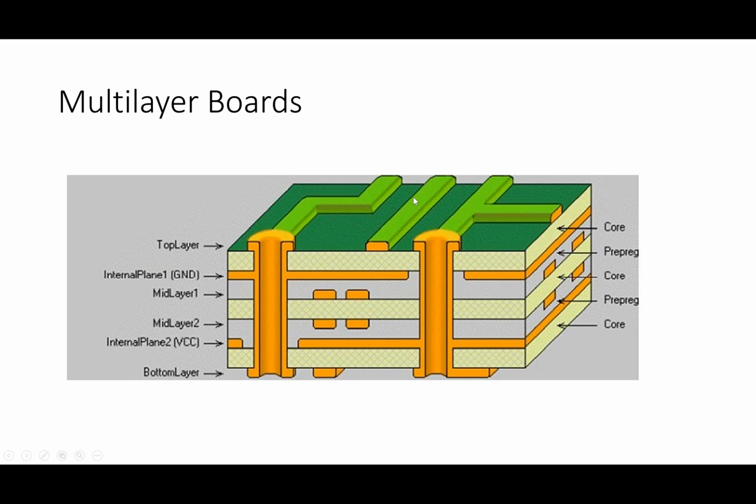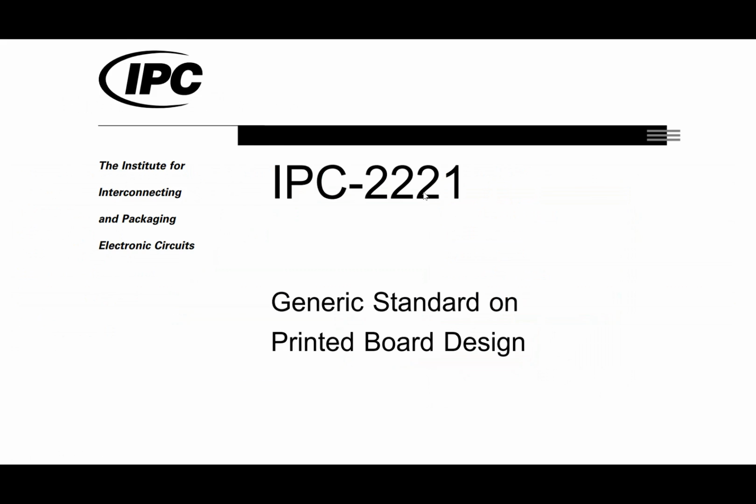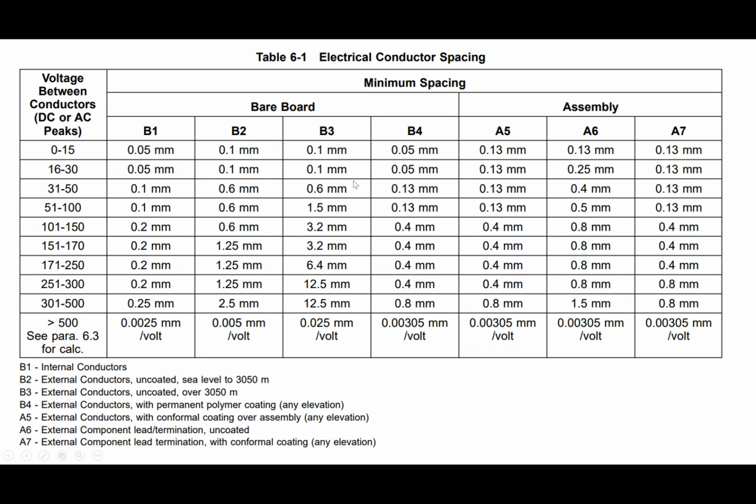There is a possibility when I have an electric field over some distance like this that I can have a phenomenon called dielectric breakdown, where I can actually get some electrons to jump from one side to the other. We want to avoid that. So one of the critical things we have is standards about what the distance between lines should be, and that distance is largely controlled by voltage, because we're trying to prevent that dielectric breakdown that you talked about in fields. So one of the things in that design standard is it gives us things like,